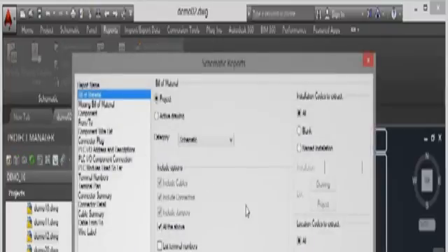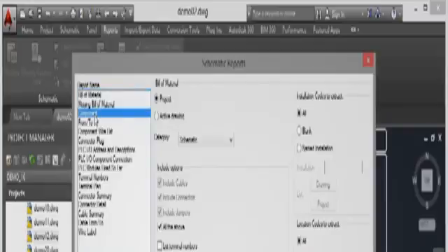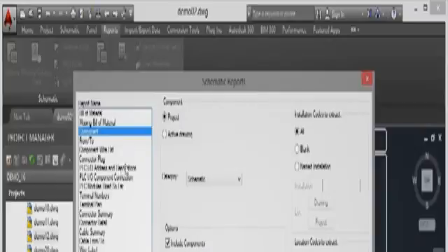Now there's a lot of information in here, and a lot of it sometimes you won't need. So for schematic reporting, we've got different types of reports. The drawing that I've got open, Demo 02, is a point-to-point wiring diagram with components in it. So I'm going to go for the component report, and you'll see that the dialog box changes. I'm going to do a component report purely for the active drawing. Category will be schematic, as in schematic components.